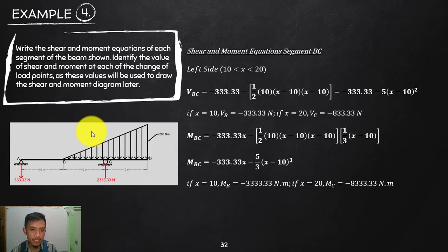Okay, the challenge here is the triangular part. Again, you need to know the centroid of your simple figures. If that is a square, that is at the middle, or rectangle, that is at the middle. If that is a triangle, that is at a distance 1/3 to the base. Okay, so again, let's say I will cut somewhere here.